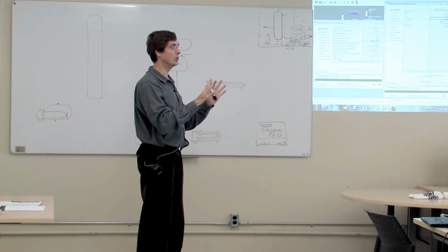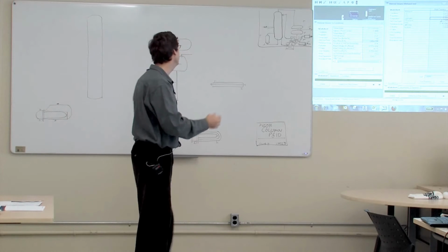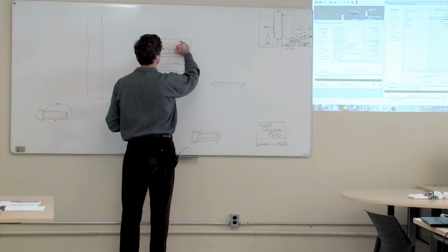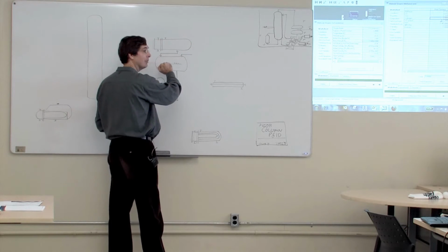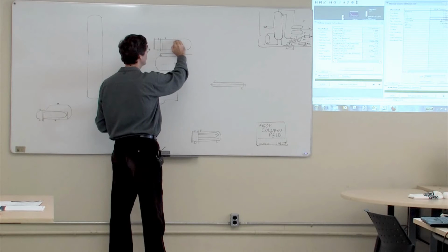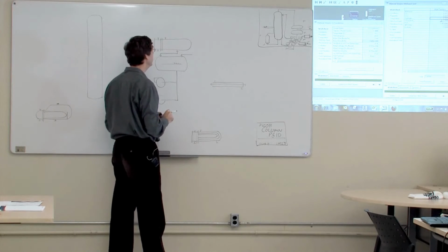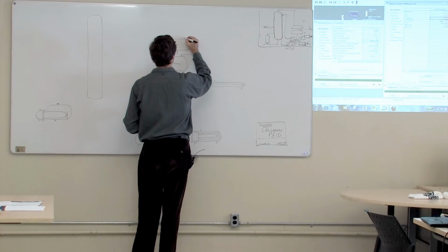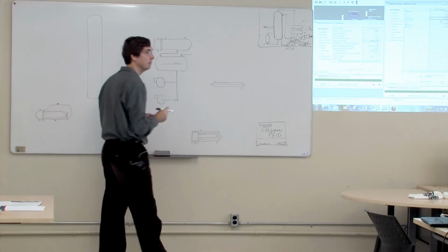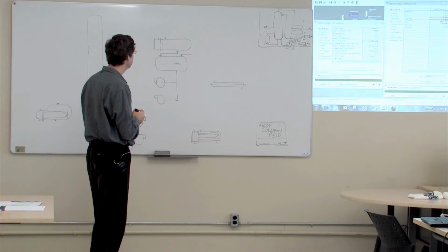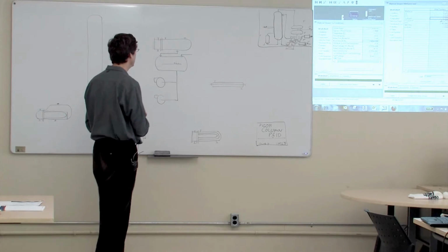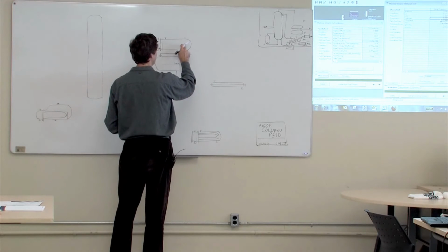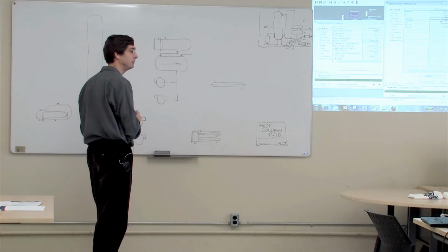And what I'm thinking is the hydrogen is actually going to drift right up to the top of the condenser here, and it won't actually come down into the reflux tank. What will happen is it'll just sit at the top of the condenser, and it'll blanket the condenser, and it'll stop me from actually running the condenser very efficiently. So I'm pretty certain that I need a vent on that condenser, on the high point. And it wouldn't surprise me if we could probably vent all of the vent off the condenser instead of off the reflux drum.